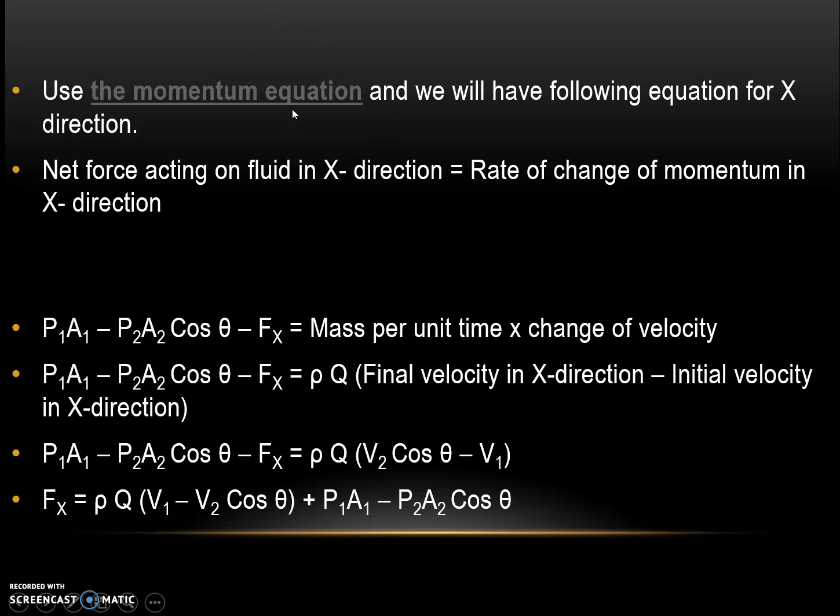Let us use the momentum equation, and we will have the equation for the x direction: the net force acting on the fluid in the x direction is equal to the rate of change of momentum in the x direction. So, it is P1A1 minus P2A2 cos theta minus Fx, which is equal to mass per unit time into change of velocity.